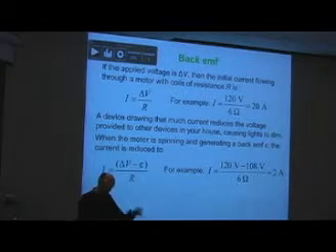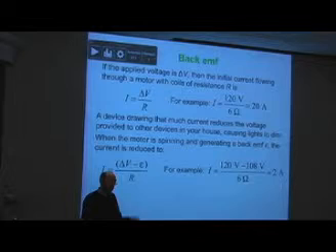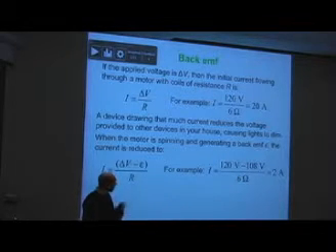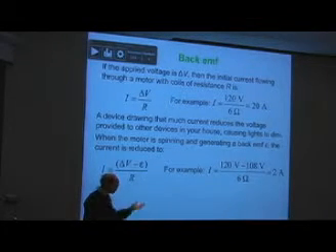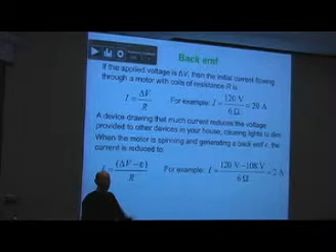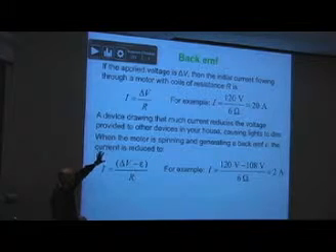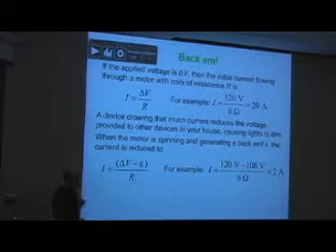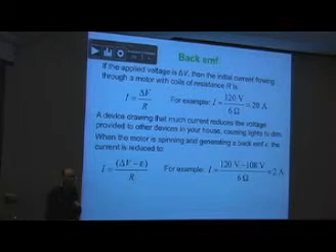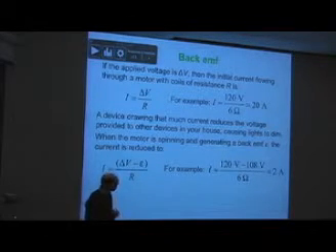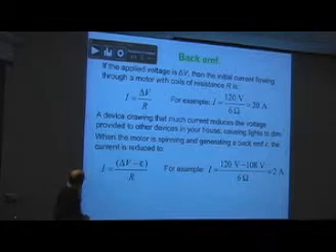We need lots of current to get the thing started. But once we have it rotating at its operating speed, the 2 amps is just needed to overcome friction and things like that, and actually do some work as well. So you start with lots of current, your lights dim, but then you're up to operating speed on your motor, and your current is actually much, much less. So all your lights come back up again.